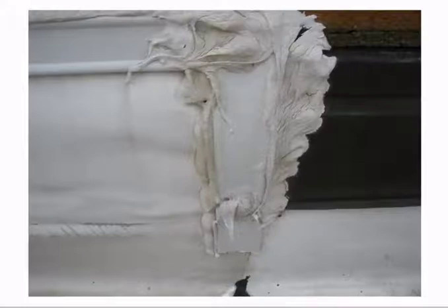Yeah. And so what's going to happen over time here is your expansion contraction of different materials. The sealant's going to break, and you will have a leak there. But a common contractor will come out and just put a little more caulk on it, keep them dried up. What needs to be done is put a flashing over that turn bar and extend over the existing a foot or so, and give that plenty of movement in there with some sealant in between it. Mm-hmm. Okay.